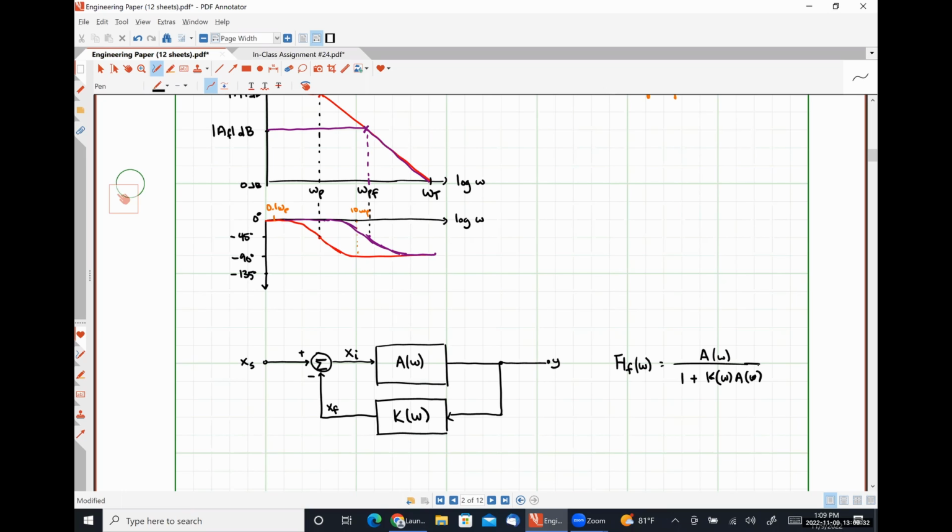We no longer have negative feedback, we have positive feedback, and our system is no longer stable. So that's where all of this stuff that we're talking about is going to come in, okay? So effectively, for every pole that our amplifier has beyond 1, we are introducing the possibility of system instability.